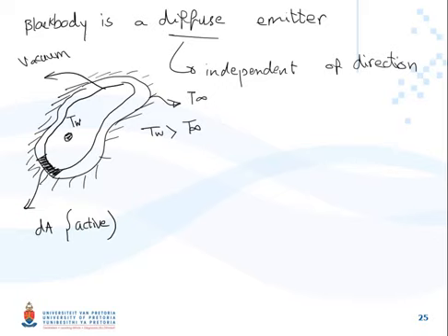So, to put it very simply, since dA, this small radiatively active area, is absorbing the maximum radiation in that particular direction, it has to radiate the maximum radiation back in the same direction, because the rest of the enclosure is not radiatively active, and it's valid for any particular given direction.